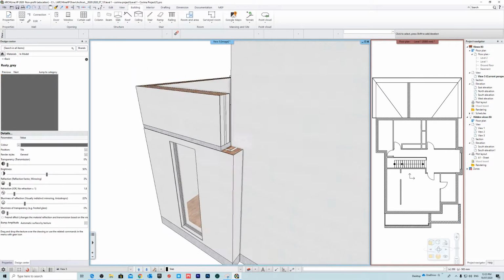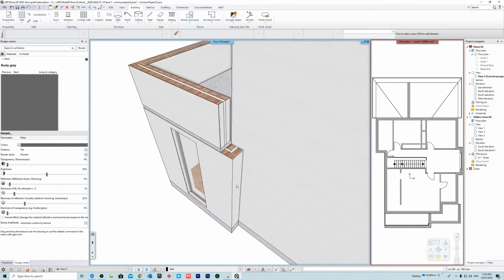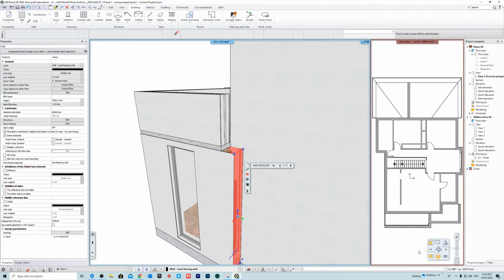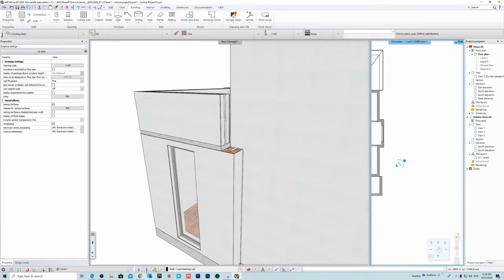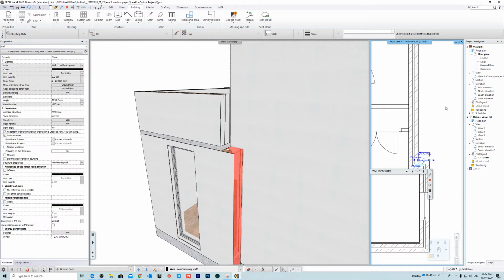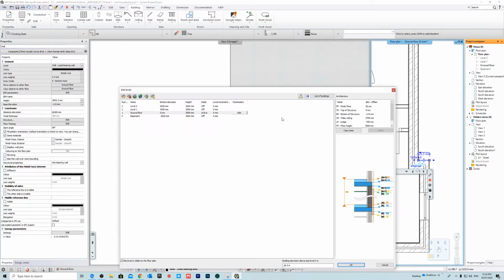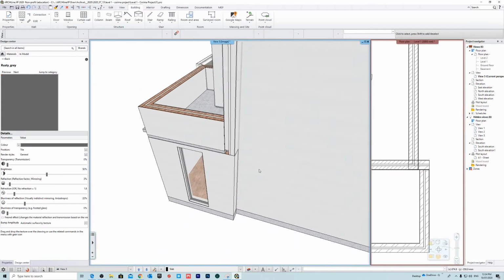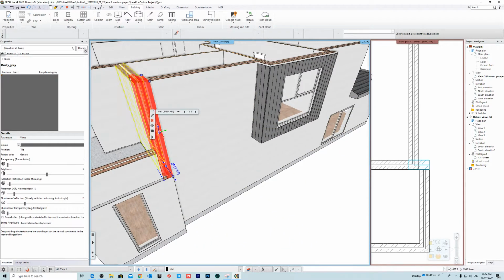Alright, so we're going to copy that. We'll go back to the floor plan, and I'll go ground floor. This little part we also need a copy, so right click floor plan, properties, copy, level 1, copy. Okay, now this needs to go down to there.